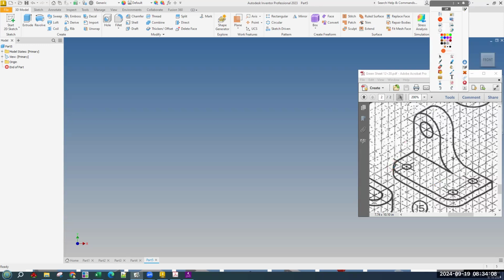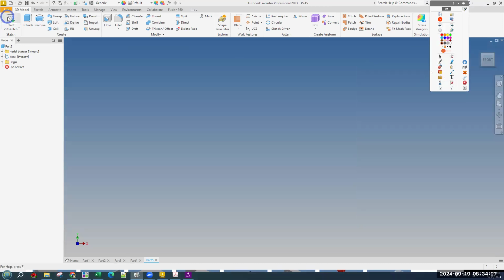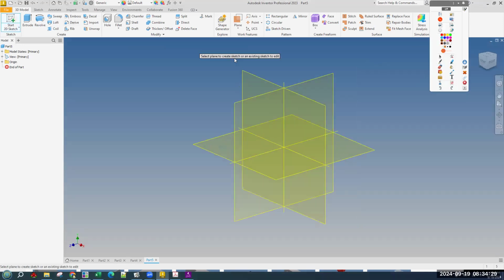If you draw on the front face, it would be 1 by 10, extrude 6. And if you draw in the footprint, it would be 10 by 6, extrude 1. If your goal is to put this sort of bracket as a footprint. I'm actually going to draw on the front. Again, for this, it really doesn't matter, but it's fine.